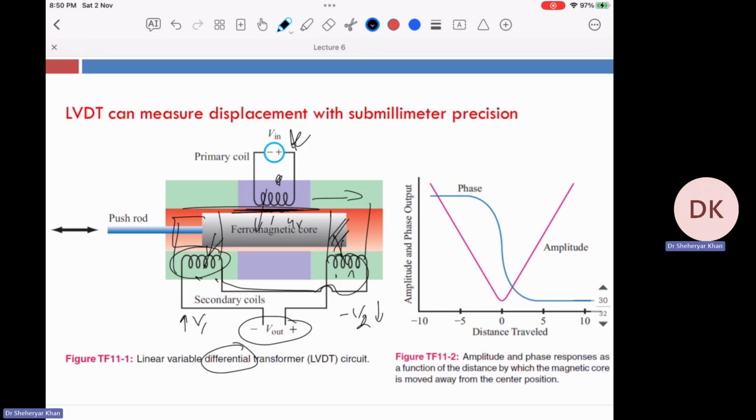Now, if you translate the motion left and right into voltage, you would get these curves. For example, if you move the other way, you see the voltage linearly increases. Now you can use a microcontroller to sample the voltage and convert it into some digital value. That shows you the amount of force in newtons, or probably the displacement, let's say millimeter, centimeter, whatever you like, right? So maybe 1 millimeter movement is equal to 1 volt, and then the number of volts multiplied by the distance gives you the final answer.